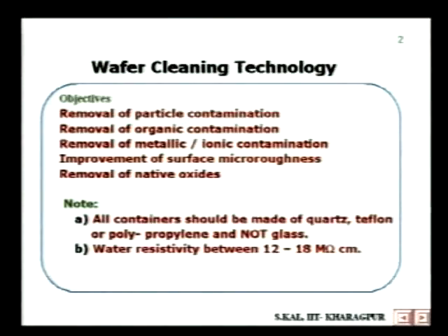In the wafer cleaning process, in many subsequent intermediate steps, we need rinsing of the wafer using good quality water. Good quality means it should be metal or ion free, and that is known as deionized water, and its resistivity should be 12 to 18 megohm centimeter.